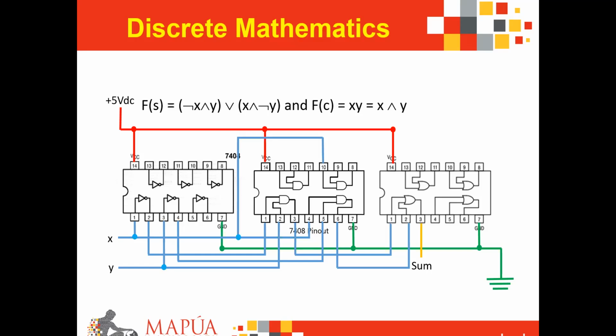We then connect again X to another AND gate, seen on pin 10, and Y to pin 9 of our AND gate in order to determine this time the output for your carry, which is seen on pin 8. This ends Module 2, Lesson 4.